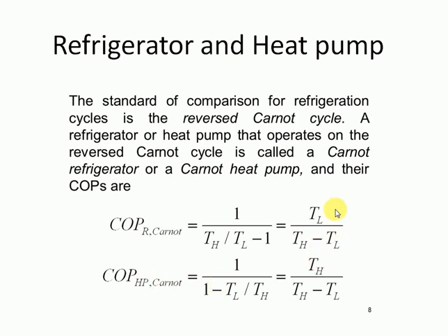Only the numerator term changes. If you analyze this, then I can conclude from these relations that the COP of Carnot's heat pump is equal to 1 plus the COP of Carnot's refrigerator. So like this, we discussed the Carnot's refrigerator, heat pump, Carnot's cycle and coefficient of performance. Thank you.